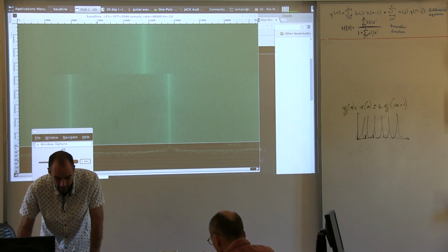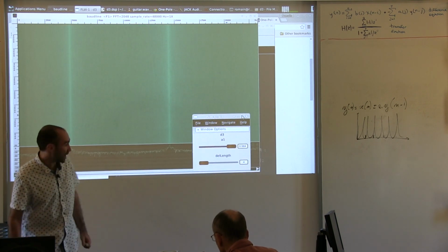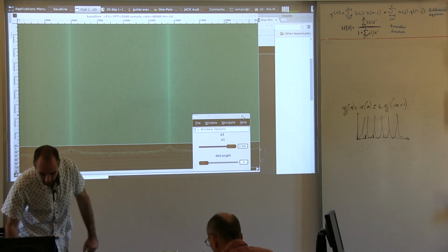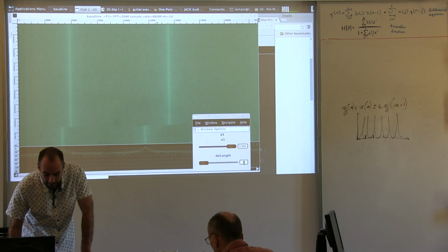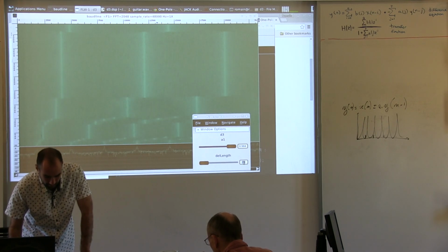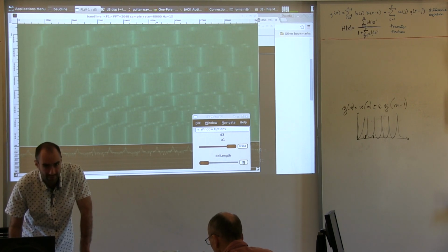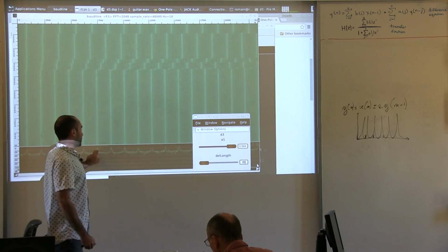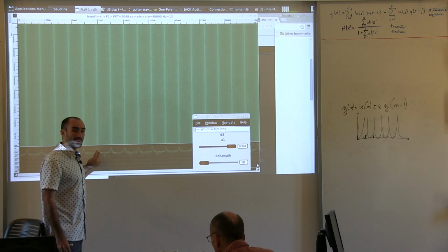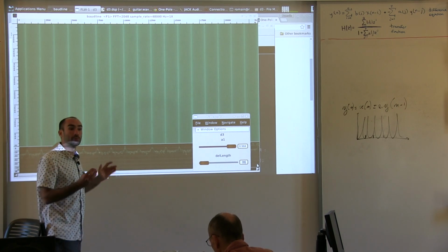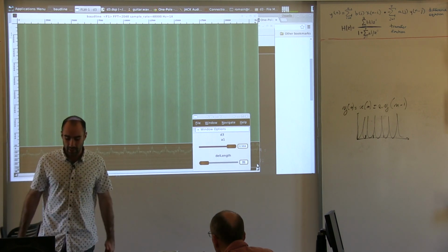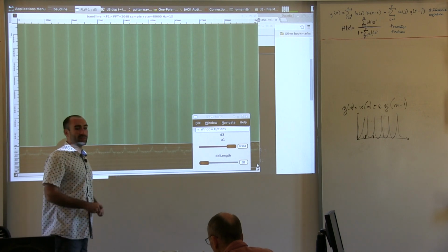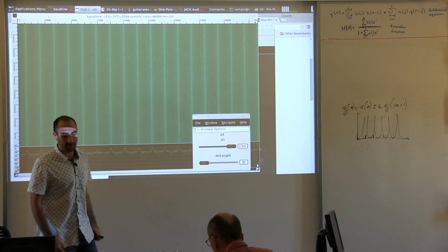There we go. So now if I move to 4, now I got two very distinct teeth in my comb filter that just showed up. And so the more samples I add, just like for the one-pole, the more compressed the frequency response of my filter is going to be. And also the narrower these peaks are going to be. And because they're narrower, they're going to highlight those frequencies even more, because they're really going to isolate them. I'm basically changing also the bandwidth of the different peaks in the spectrum, highlighting more these very specific frequencies.